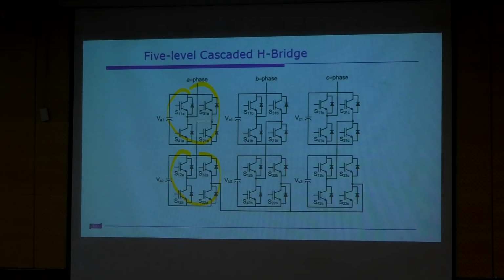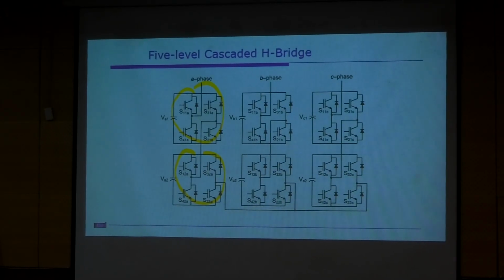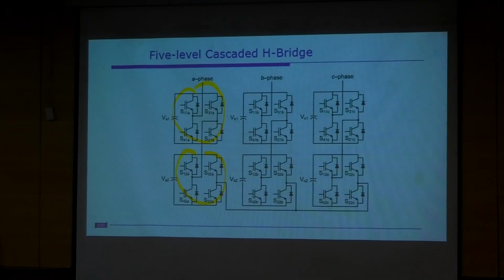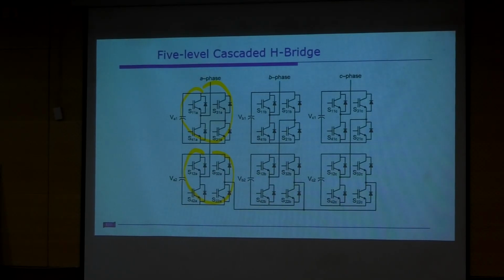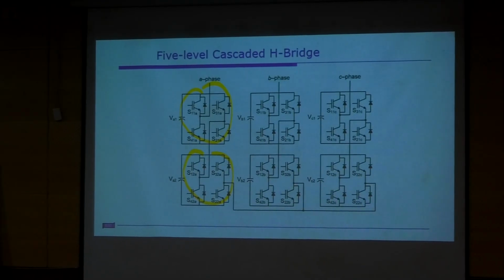The modulating signal is responsible for the output voltage and frequency generation, so you can't duplicate it. Therefore you require 4 carriers. With 8 switches and 4 carriers, each carrier interacts with the modulating signal and generates the firing signal for a complementary pair.